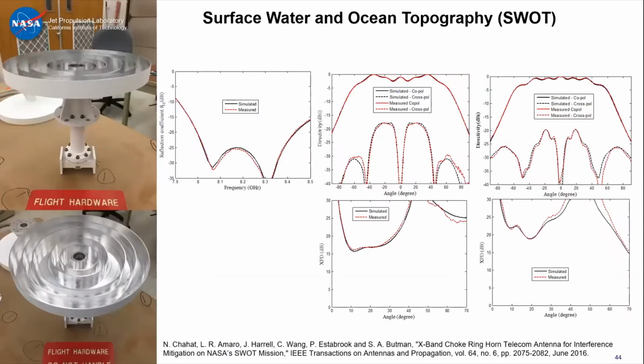So we designed this antenna, which is an externally corrugated horn combined with a polarizer. Like I said, each port provides one of the two polarizations. You can see here at the 60 degrees that we get a very good cross-polarization discrimination, and that's what we see on the bottom. In free space, we have more than 25 dB of cross-polarization discrimination.